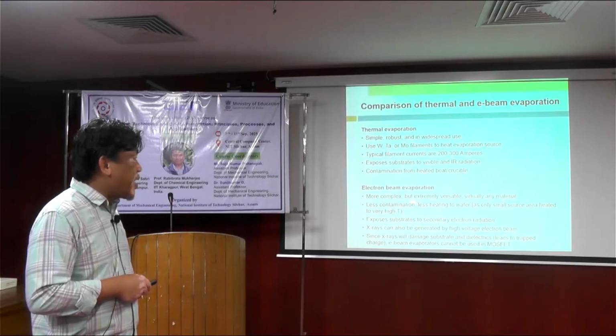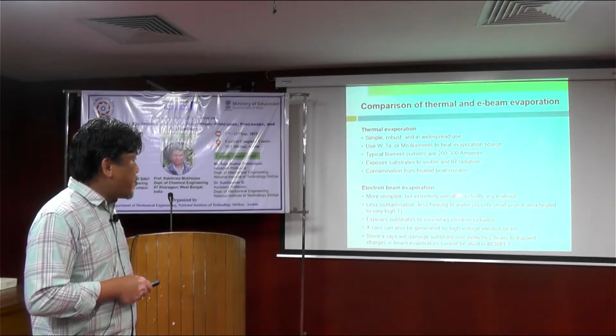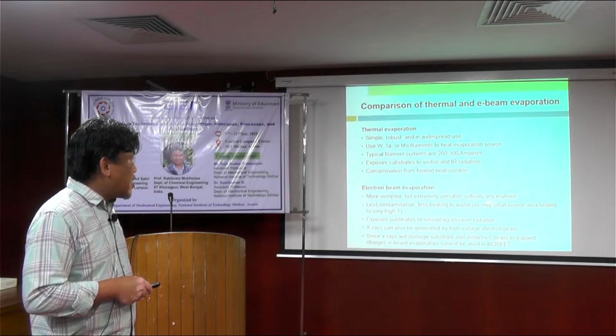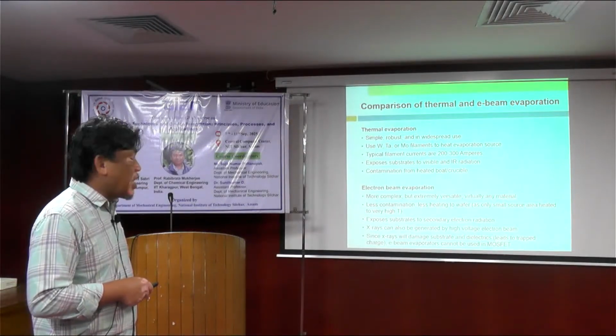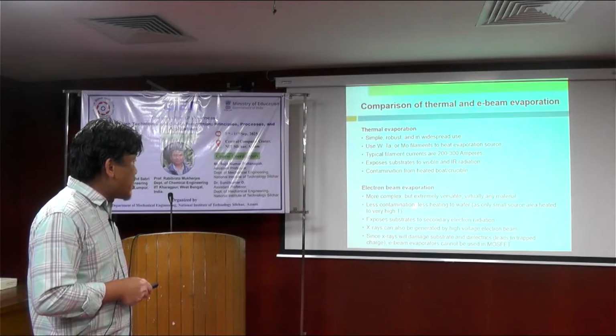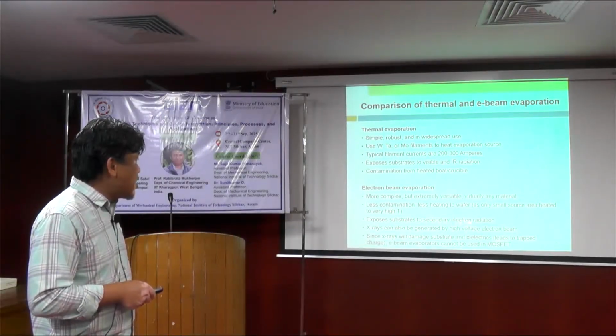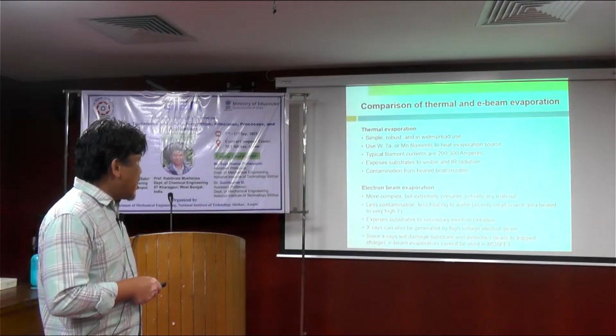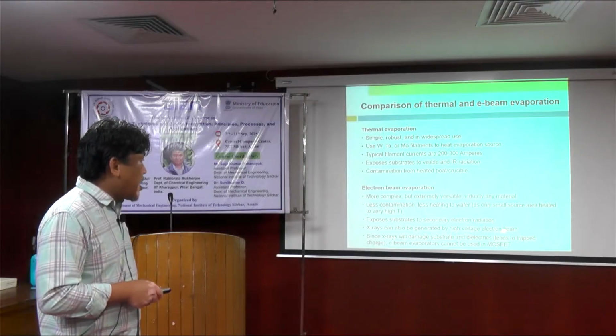You can evaporate many materials, virtually any material, basically up to 3,000 degrees of heating. And there is less contamination and less heating to the wafer, but it exposes the substrate to secondary electron radiation, and X-rays can also be generated by the high voltage E-beam.